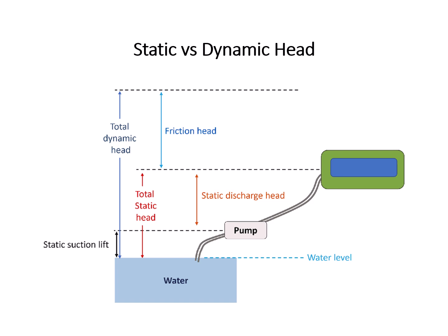It is very important to know that the static head is independent of the flow rate. It exists even if the pump is off, and it can be positive if it is a head, and negative if it is a lift.